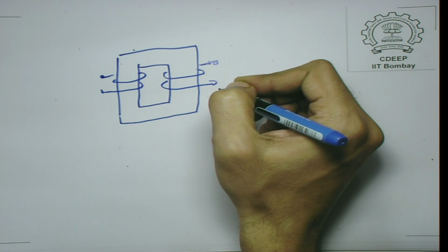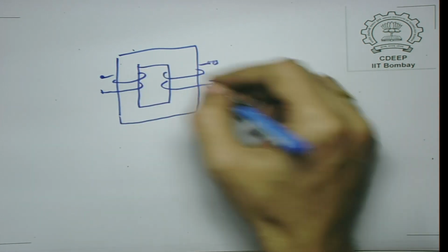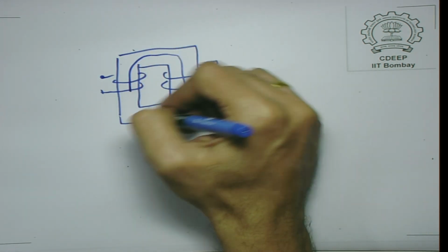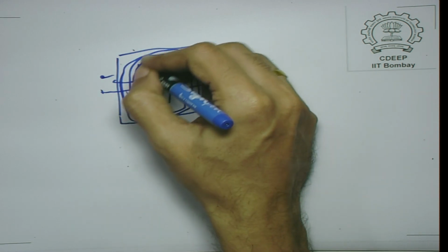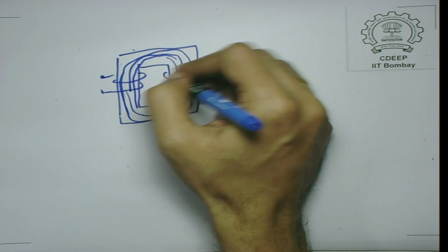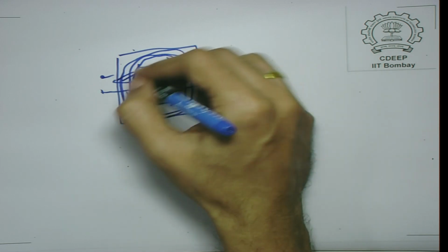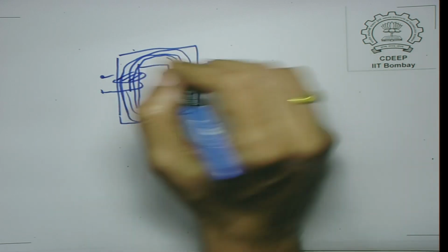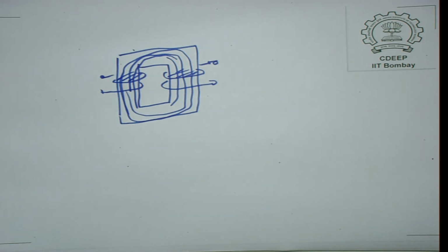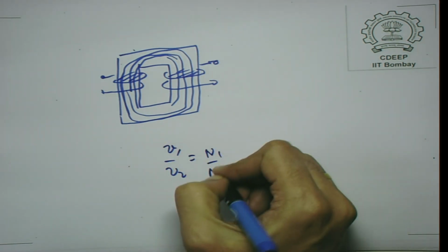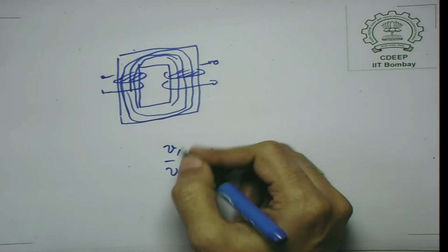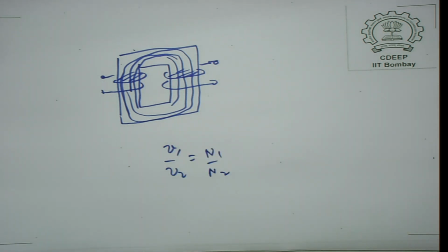Suppose you have got these two coils, and the flux linking one coil is equal to the flux linking the other. So, if I compute the flux, B dot ds, here as well as here, it is exactly the same, then we have the ideal transformer equation V1 by V2 is equal to N1 by N2, which is true during transient conditions as well as in sinusoidal steady state conditions.